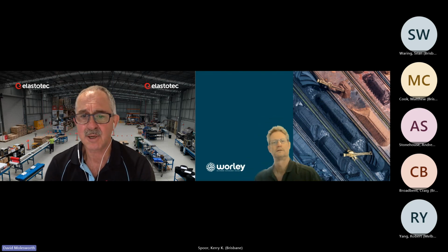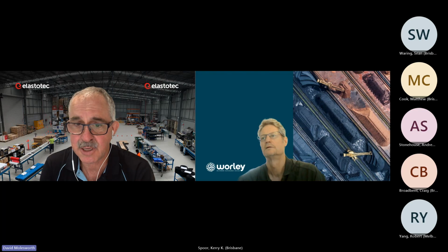That's basically it. So if you look at the iron ore industry in WA, for a long time they were running smooth direct bond ceramic on their non-drives, and they had the dimpled ceramic on their drives. And they ran into a lot of problems with the build-up on the smooth ceramic, and that was causing belt tracking problems. When it got bad, it was breaking cords. And then they moved to hot cast polyurethane. So you find now Rio Tinto and BHP and FMG have all got hot cast polyurethane in their specs.